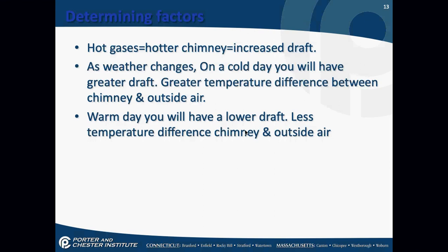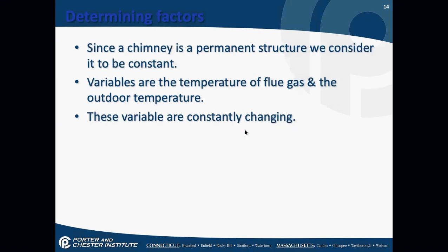Now you think to yourself, why do I use oil on a warm day? Give me an example. Why do I use oil on a warm day? For your hot water. Hot water heaters. They have to run year-round. So warm days we have lower draft. We have to be very, very aware of that.